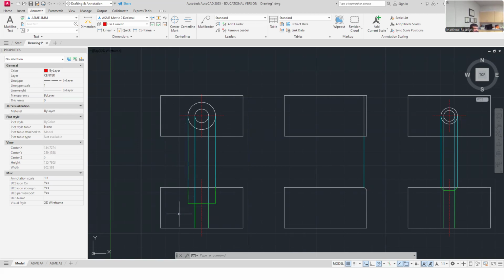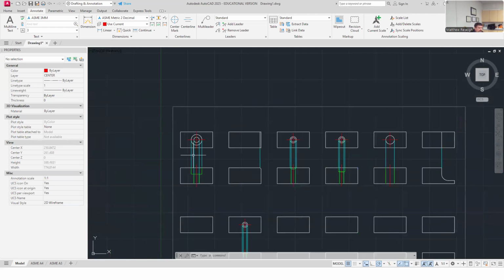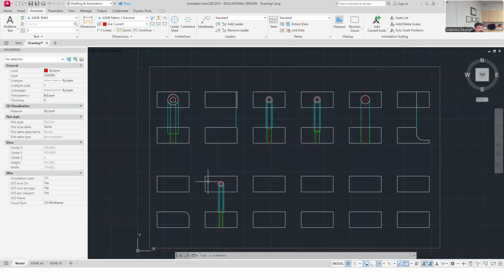In the front view I have width and height, so the terminology changes from one view to the next. In my right side view, I have height and depth. In the front view, I have height and width. In the top view, I have depth and width. So I think you have a question that is going to try to confuse you on which view shares features.